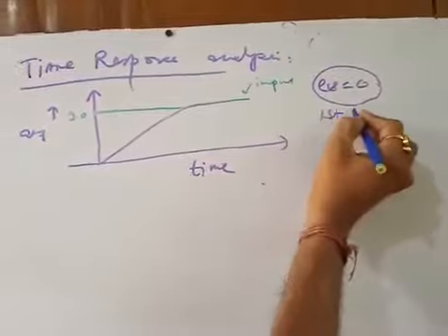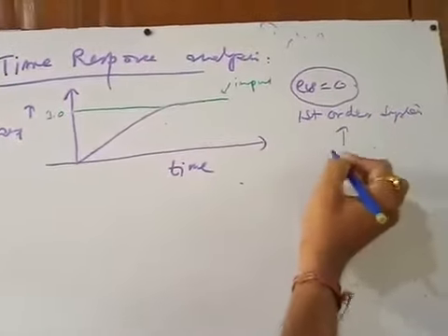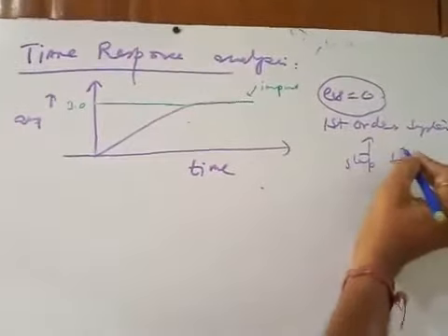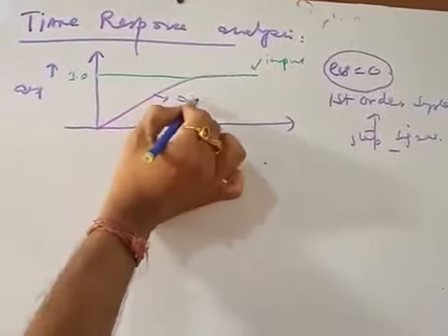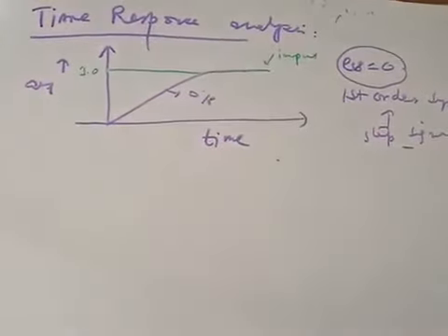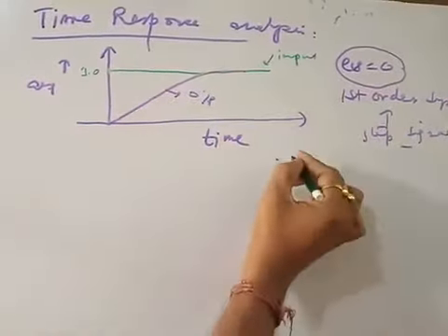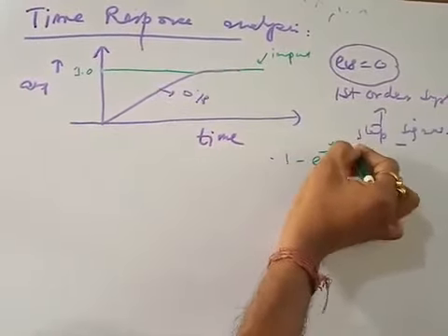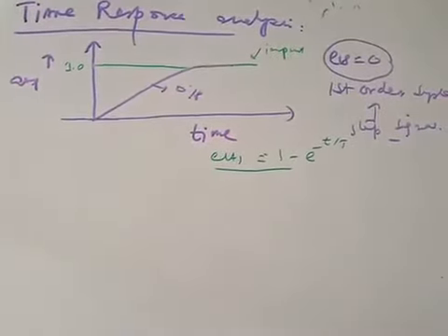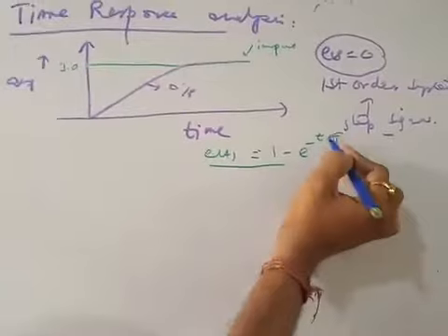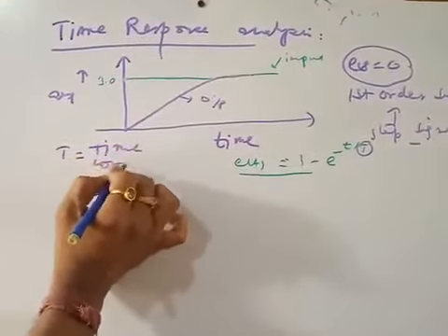First order system, when applied a step signal at the input side of it, you get the step response. So this is the output signal. Now see how I have drawn the curve. This curve is drawn based on the formula 1 minus e to the power minus t by T. This is your C(t). See, what is this T? This T is known as the time constant, right?